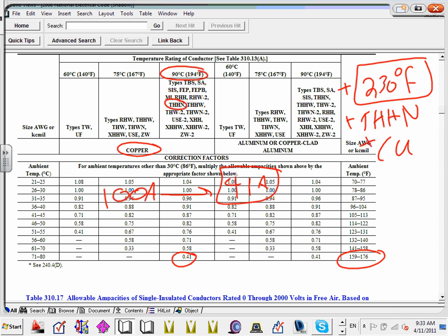Let me give you a secret. Secret, guys, now moving on. If you're using feeders, don't you ever group feeders. If you use feeders, guys, send a circuit directly. When I say feeders, 100 amp feeder, 125 amp feeder, send a conduit per circuit, so you don't have to worry about this mess.